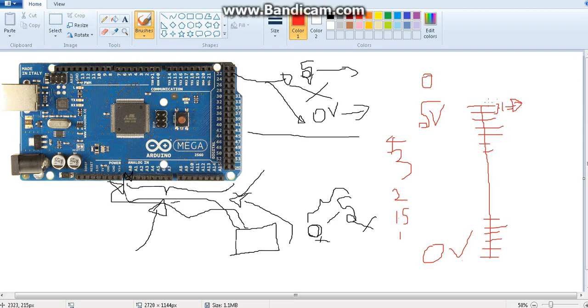What Arduino will do is take these 1024 units as a comparison with 0 to 5 voltage, or in other words, 5 voltage will be divided into 1024 units by Arduino. So Arduino will have a scale, and that particular scale is none other than a divided 5 voltage. So 5 voltage will be divided by 1024, and 1 unit will mean that voltage amount. If you are giving that voltage amount, Arduino will take it as 1 unit. You understand?